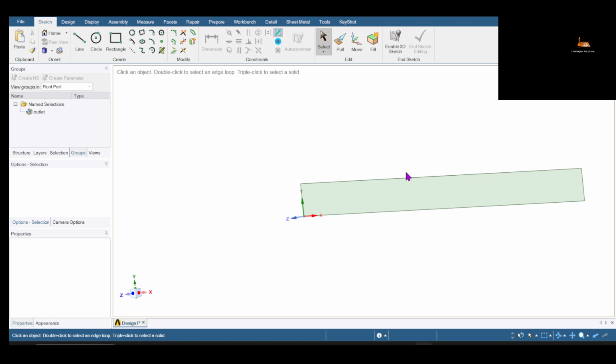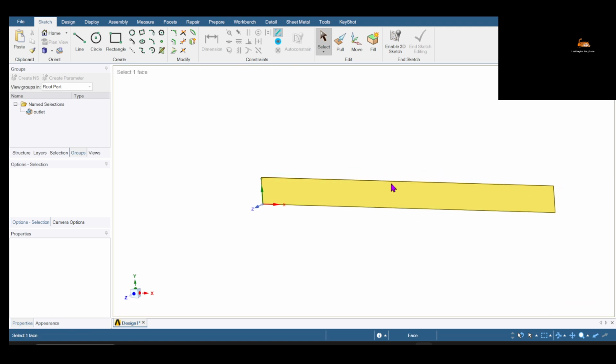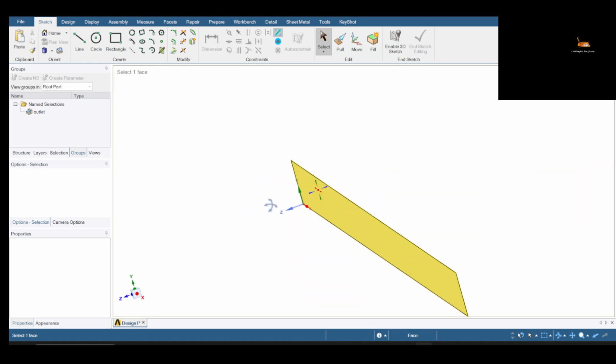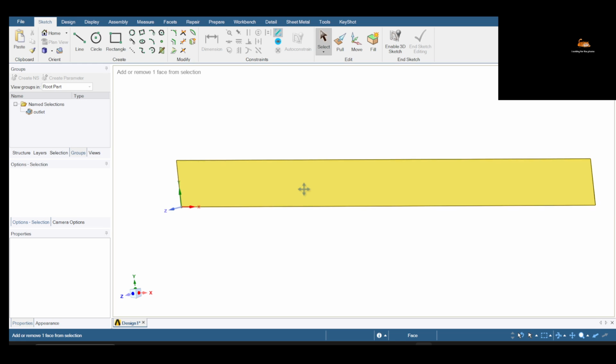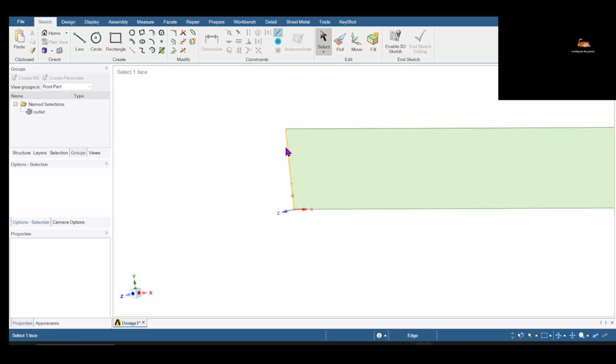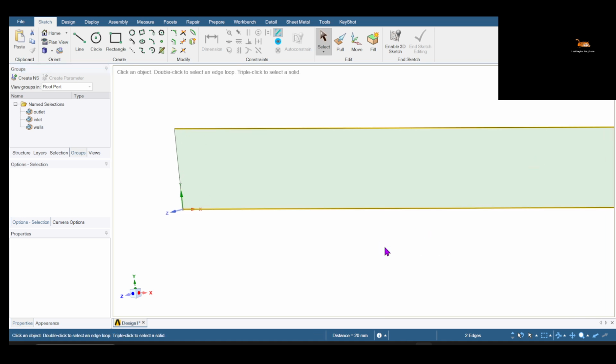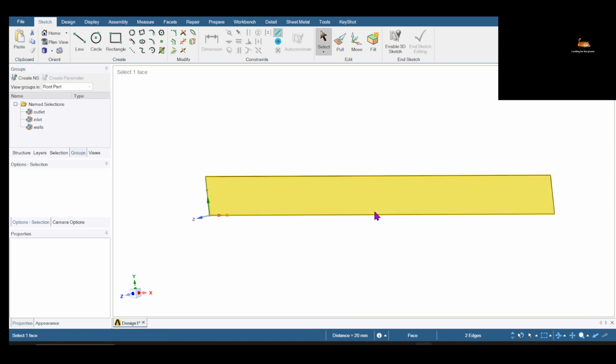Then we can click on it. I'm doing the zoom in and zoom out with the help of my mouse. To drag it I'm pressing the control. The scroll is zoom in, zoom out. If you press scroll and rotate, it will rotate, and if you want to pan it, you can press control and middle mouse button. Then I can click here, press Ctrl G, it is inlet. And these two are the walls. Control G, walls. These things are required for this pipe model. It's a simple 2D model, so we'll see the 3D model later on as well.